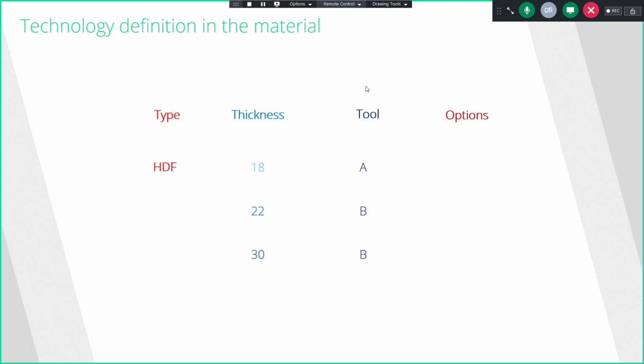So what can be the difference? We may have some differences in the tooling options, for instance, step over. We can turn it off if the part is thin enough, or enable it and define what the step value will be. As you can imagine, this can be done for different materials, for MDF, for instance, and plywood and so on. You can apply different tooling options, which is very convenient.